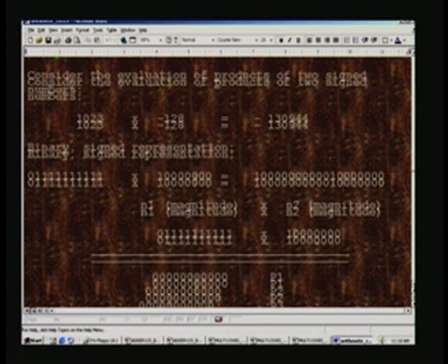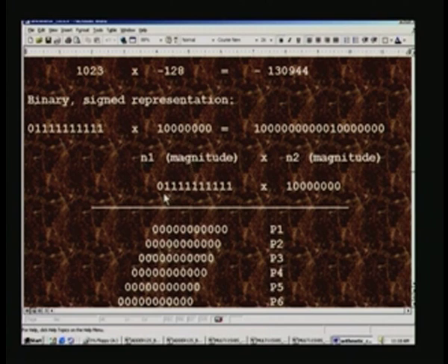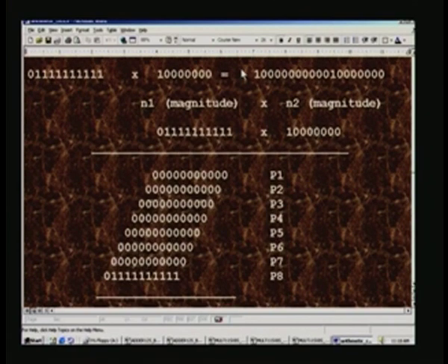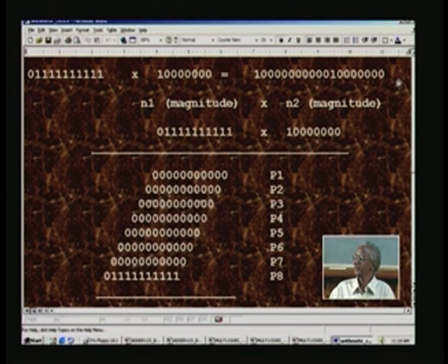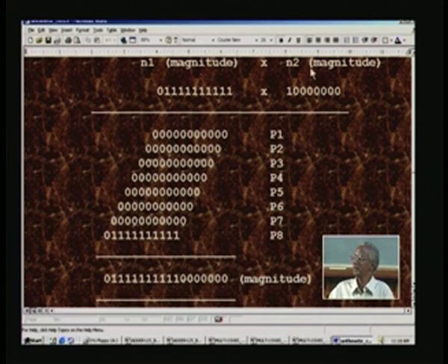As mentioned before, we will take only the sign of these numbers, which is this here. This happens to be exactly the same, and for 128 minus and plus happen to be the same, and this being a positive number, automatically the same number is put here for magnitude. So we can evaluate magnitude merely by taking the 2's complement of any number. For example, you can take a 2's complement of this, and out comes the magnitude of this number, and we can identify this number as negative by inspecting the MSB, which happens to be 1.